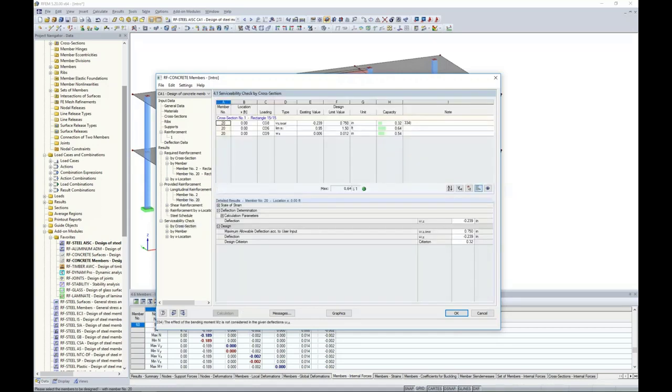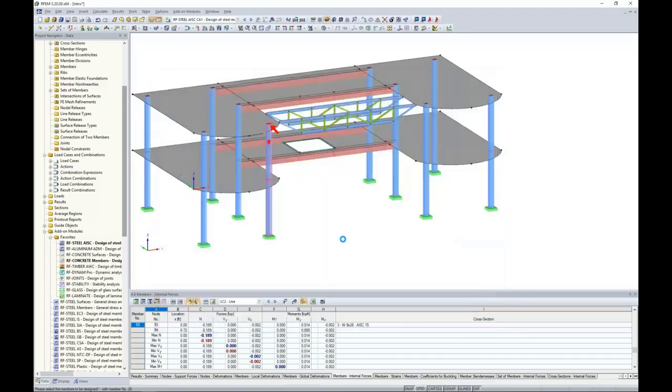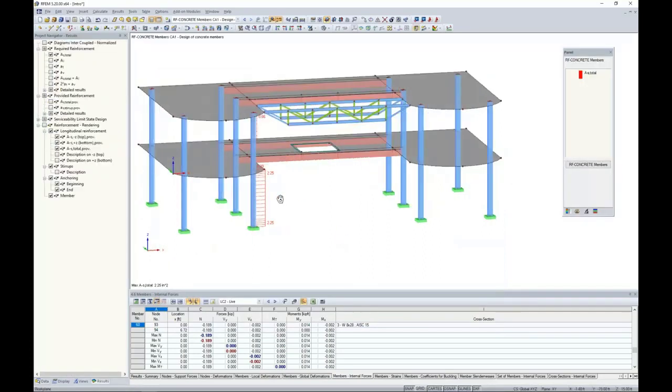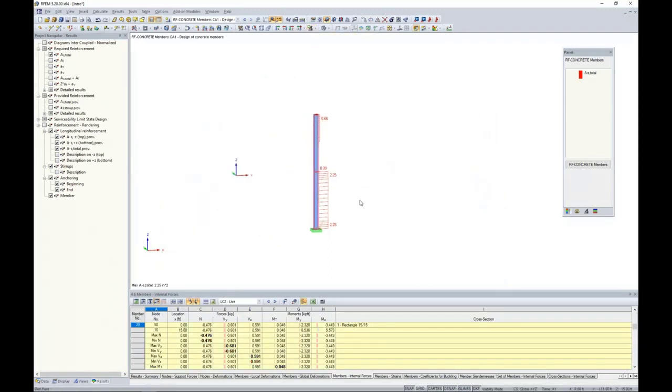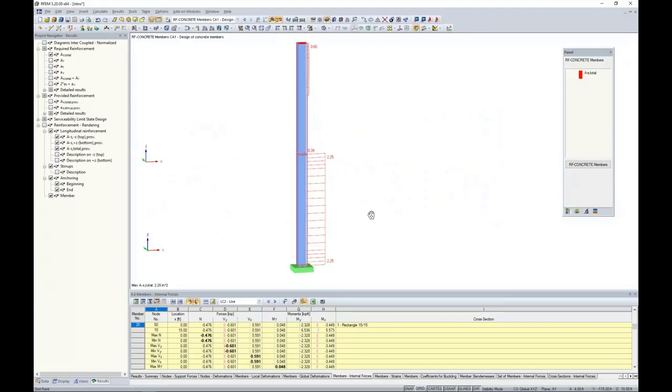We will check serviceability as well. Again, that's including that crack width. It's also including deflections, and we'll give you a ratio check here. We can view this information graphically back in RFEM just like what we saw with our steel members. So maybe I create a user-defined visibility with only my 2 columns here, and I can zoom in.